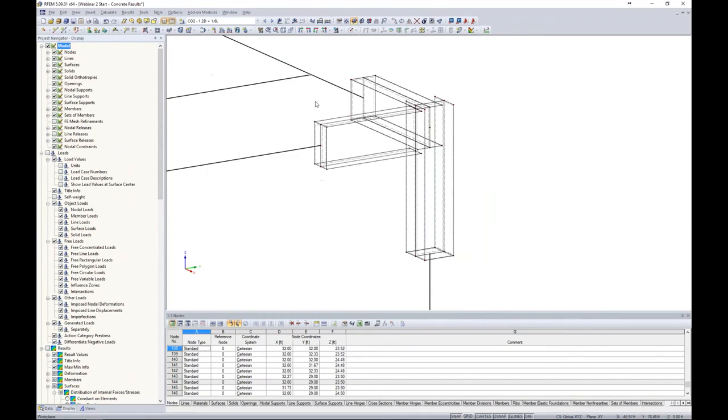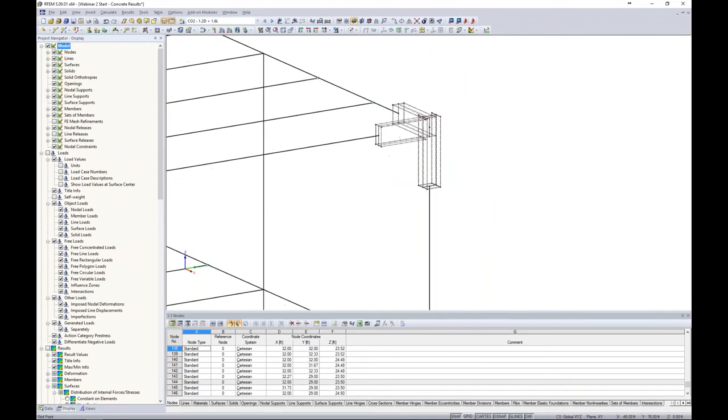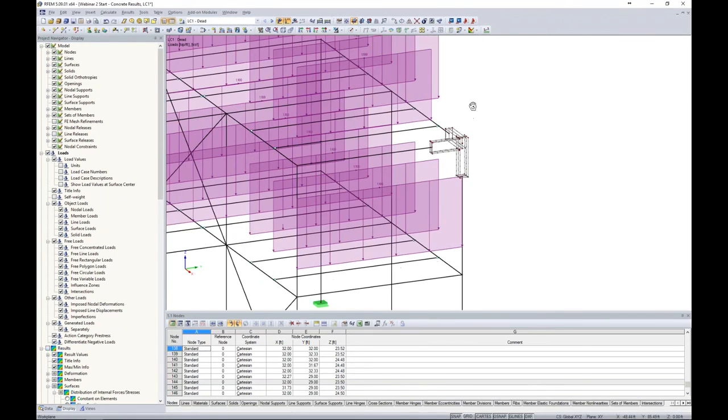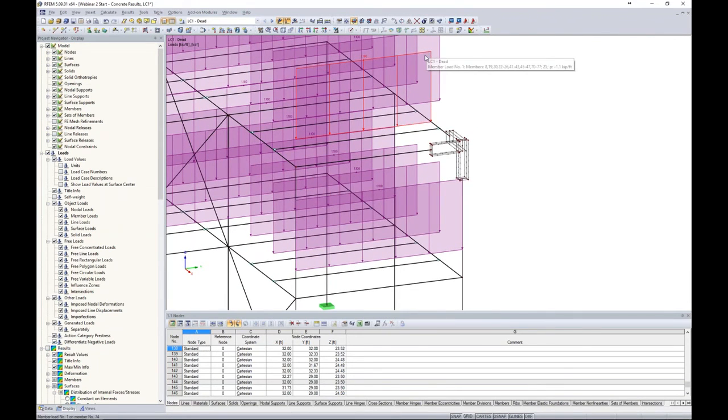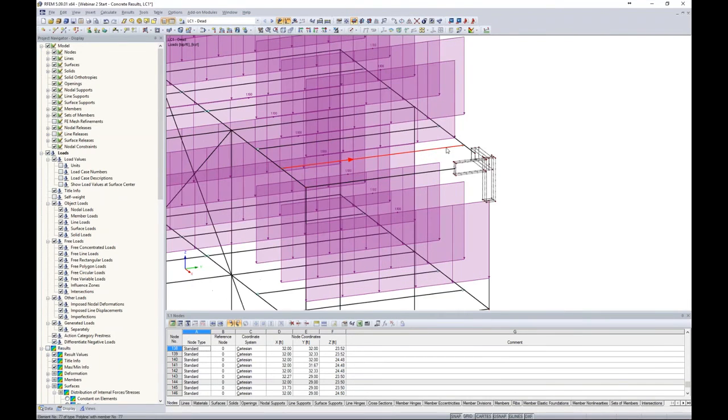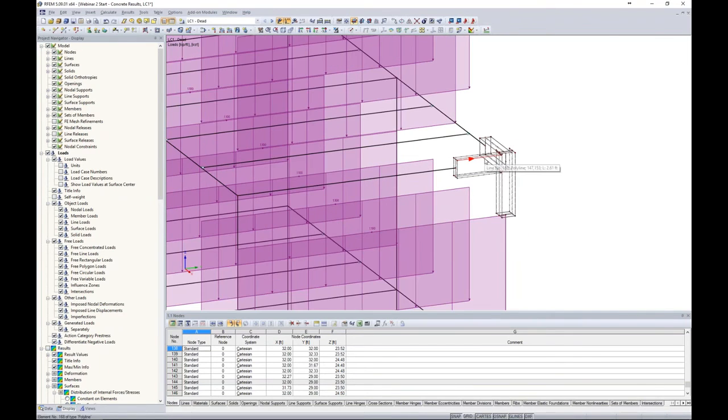So we're almost ready to run our analysis, but let's take one final look at our applied loads. We will jump to our dead load here, and see our applied loads. Now these are member loads applied in kips per foot along our various steel members, but we no longer have members, so we lost those applied loads. Well, in a similar sense, we can apply the same load magnitude, but this time as a new line load.